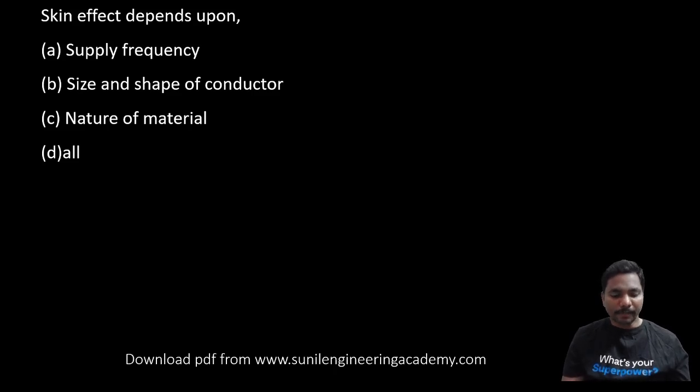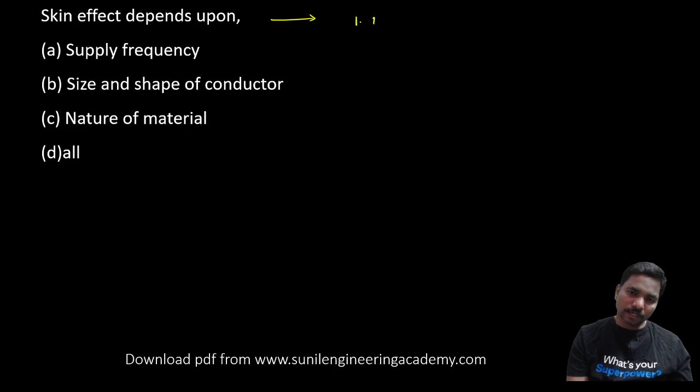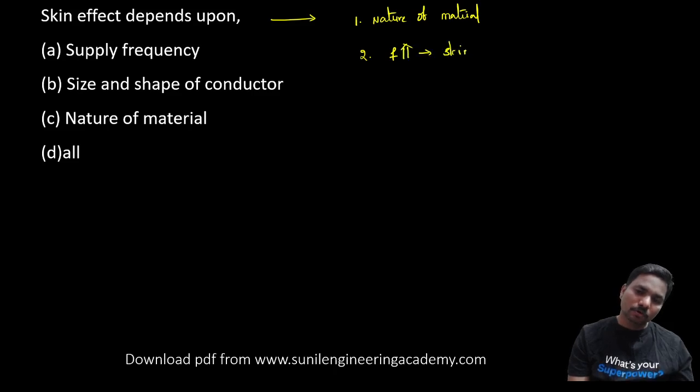Here, skin effect depends on dash. Skin effect depends upon, first one, nature of material. Okay, and the second one, frequency. As the frequency increases, skin effect is more. So alternating nature increases, so skin effect is more. And third one, diameter. As the diameter is more, skin effect is more.